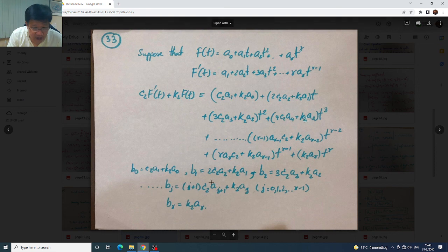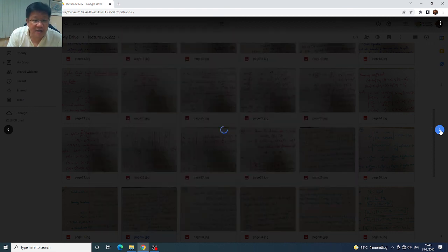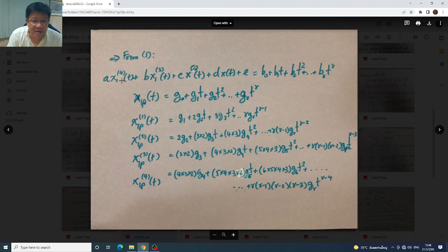Okay, and in general form it can be written here based on this observation. Again, c sub 2 here is the damper coefficient, not the constant, the second constant in the complementary solution. So from here, this is the general one, with small a, b, c, d, e: a x, b x, c, d, e. This is the left hand side and this is the right hand side.